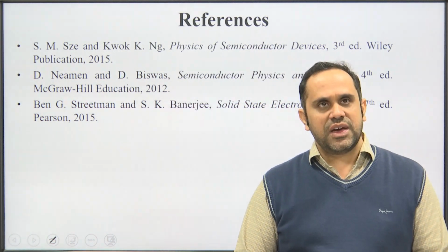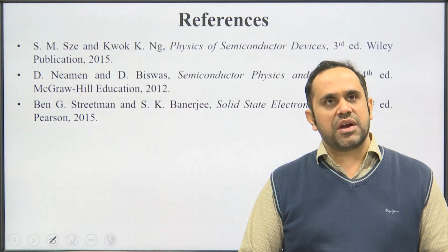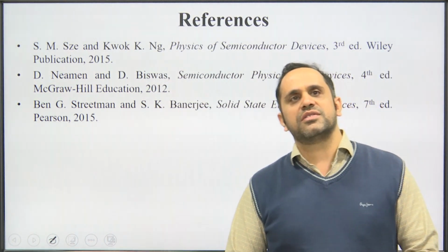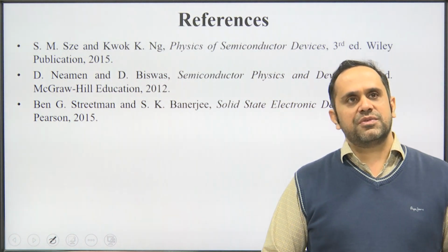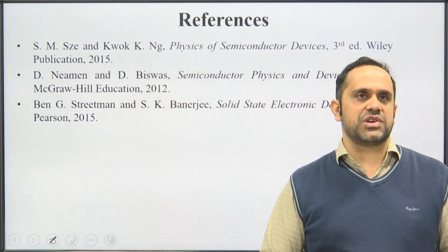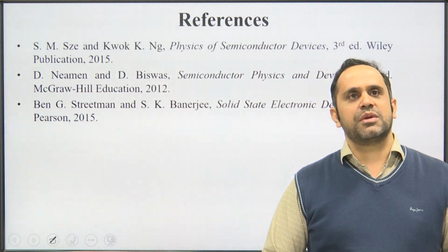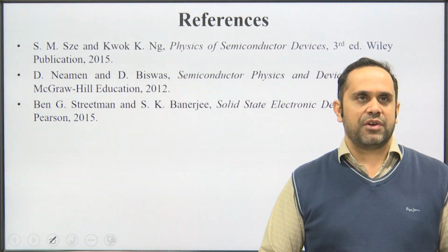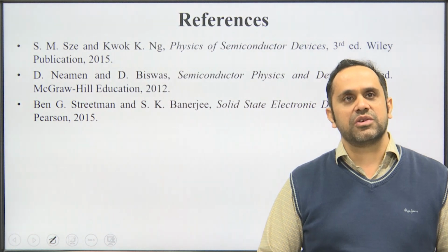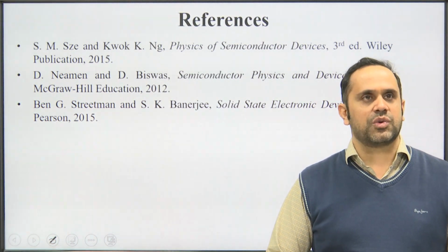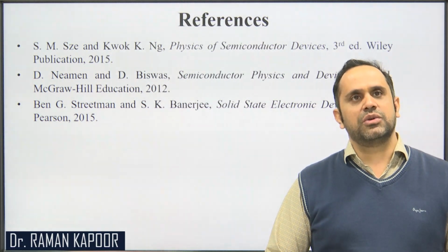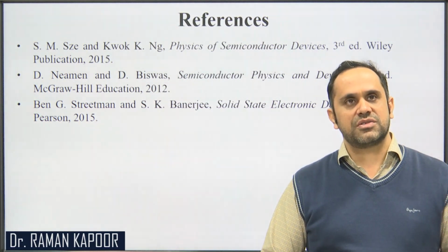Just to summarize, we have studied some of the theoretical properties associated with different semiconductors, like optical, thermal and phonon properties. Plus we have analyzed what a heterojunction, a junction between two dissimilar semiconductors, looks like. When you produce such a heterojunction, you introduce strain, which tends to produce very high mobility devices and is quite useful, provided you do not exceed the critical thickness of the strained layer.